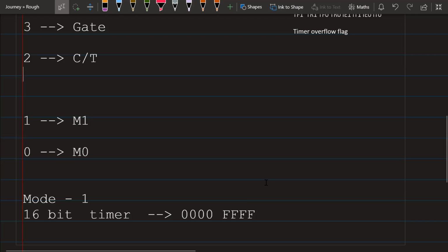So what I'll do, initial value I'll set to 9. So the counter will keep toggling 9 to 10, 1 millisecond. Your timer flag will be set. Again, it will go 9 to 10, 1 millisecond. Timer flag will be set.